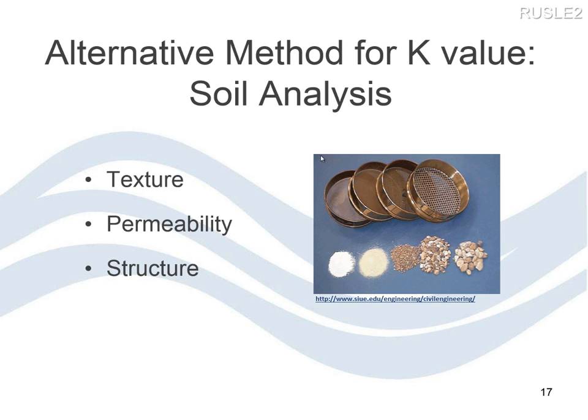Permeability is also a lab test, so we can come up with a permeability class, in inches of water per hour, and that's a standard lab test as well. Then soil structure: texture is the percentage of sand, silt, and clay, while soil structure is how those particles are arranged. So there's texture and structure. Those are the two primary soil quality variables we're interested in for deriving a K factor.